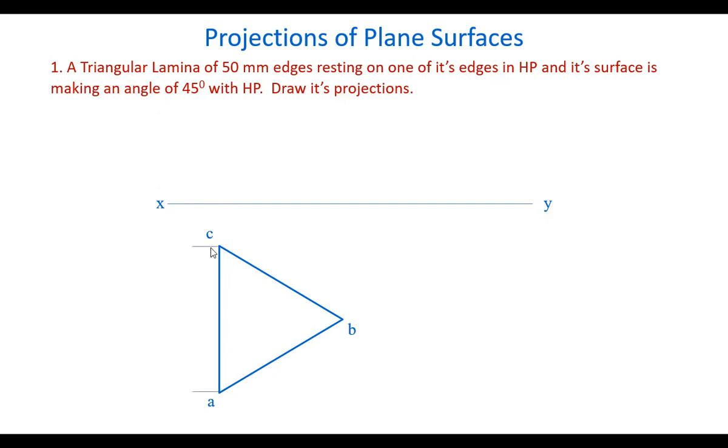Now, show the dimensioning and draw the front view. Already we have seen this. So, this is the front view. After getting the front view, we have to lift. Which side? I will lift this point B. That means the entire plane is lifted upwards like this, keeping points A and C on the horizontal reference line. So when you lift it up, this surface makes an angle.